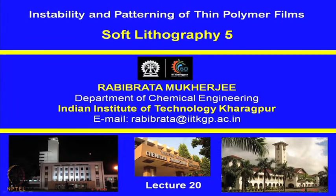Okay. The third aspect that sometimes really affects the cost of a lithographically fabricated stamp is how much area you want. Photolithography is a parallel process, but many of the direct write methods like electron beam lithography and focused ion beam are serial writing methods. We haven't covered these techniques in detail, but you can always look into the literature. They can produce features with extremely low lateral resolution, down to let us say 20 nanometer.